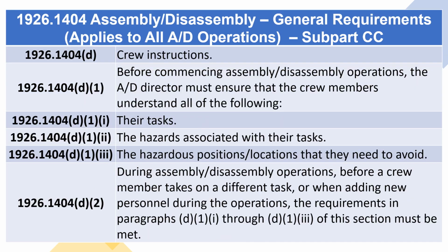1926.1404(d), Crew instructions. 1926.1404(d)(1). Before commencing assembly/disassembly operations, the A/D director must ensure that the crew members understand all of the following: 1926.1404(d)(1)(i) through (d)(1)(iii). Their tasks. The hazards associated with their tasks. The hazardous positions/locations that they need to avoid.